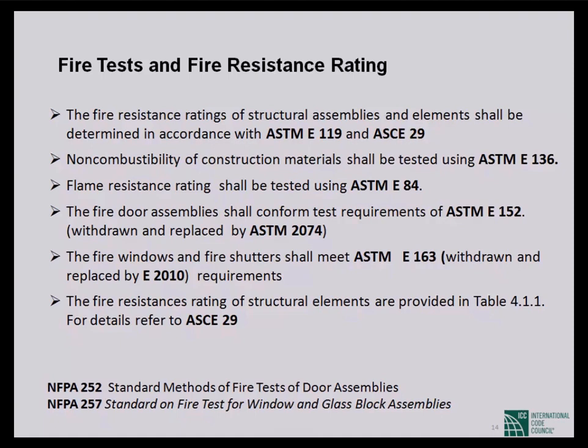In reality, sometimes we do not use ASTM, but when you read the ASTM, sometimes it will refer to an NFPA. NFPA 252 is a standard for testing doors. NFPA 257 is the standard to test windows. All the same, but a different type of standard. NFPA 252, 257 is similar to the ASTM E152 modified by E2074. These are the testing methods for windows and doors. So you can see the ASTM E163, which is testing standard for windows, which is replaced by E2010.